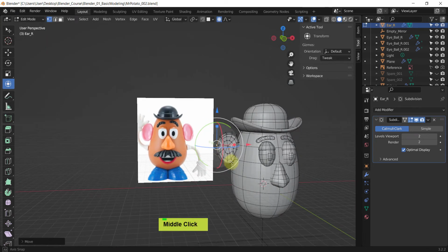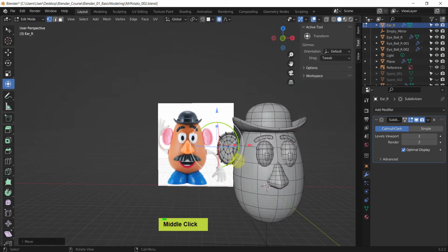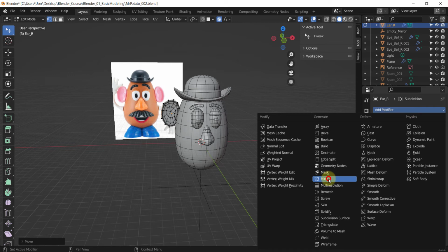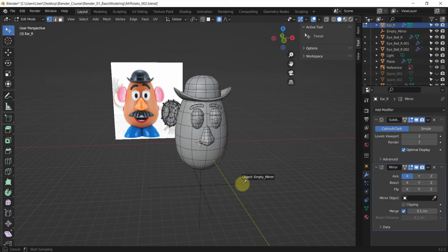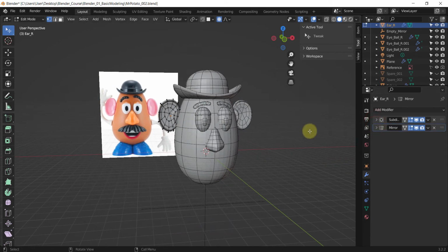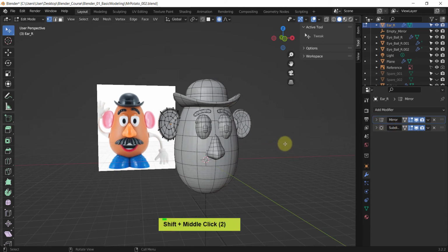That's great. Because we have two of these, I will use the symmetry, and change the order a little bit later. So picking, we don't need to cut or flip or anything from the right to the left, but we definitely want to change the order. It's usually a better technique if you keep structural modifiers at the first stage, so perform it first, and then the finishing modifiers like subdivision are a little bit up.